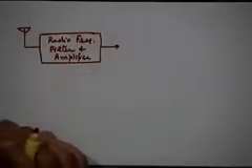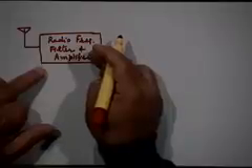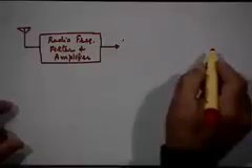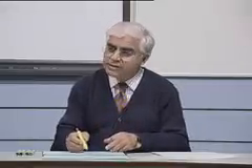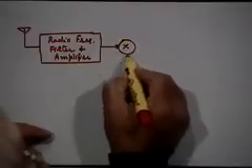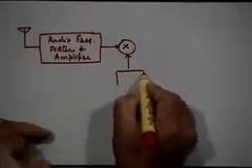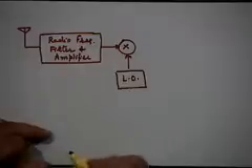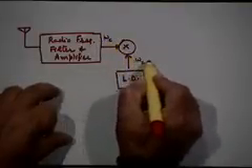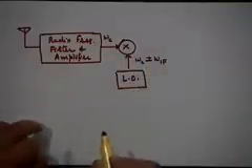Now this signal, you have tuned it to a certain frequency, right? It may not be very highly frequency selective at the moment, because we are saying that selectivity will be put somewhere else, right? But you have roughly tuned it to the frequency of interest, right? And what should you do? You should convert this signal now to an intermediate frequency signal. So this is like the frequency translation we were discussing yesterday, using a mixer, right? And a mixer will have two inputs, one the incoming signal here and a local oscillator, right? So this mixer, which is again a multiplier, takes the other input from a local oscillator whose frequency is, suppose this is omega c, right, this will be omega c plus minus omega IF, right.